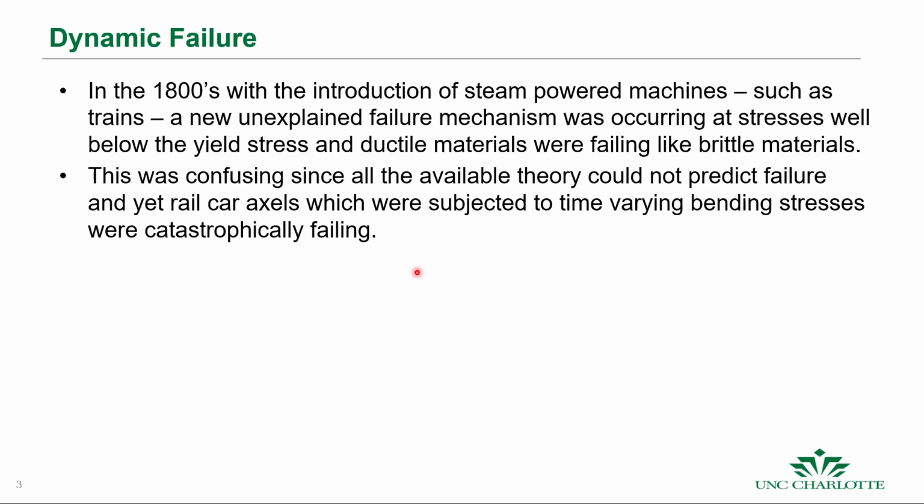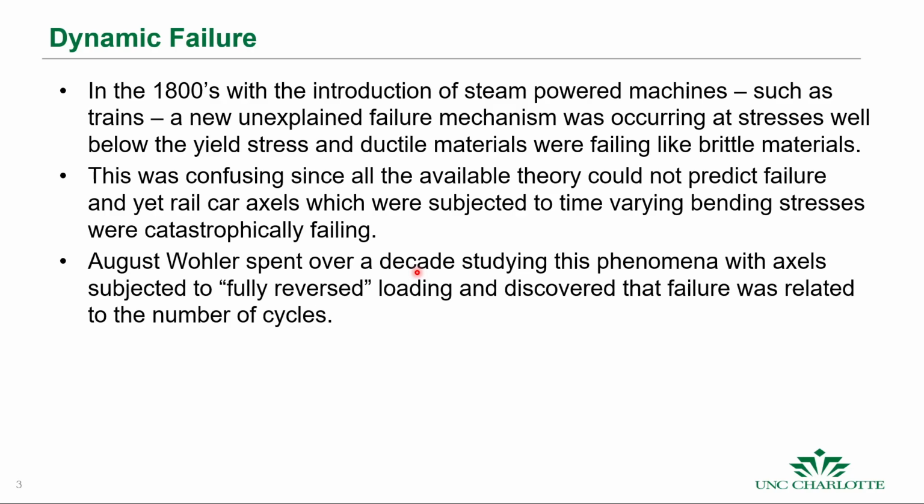We now know that it's because of time varying bending stresses, even bending stresses that are well below the strength of that material. So August Wohler spent over a decade studying this phenomenon with axles. And his axles were subjected to what we call fully reversed loading. That's where we have a positive and then negative load, and it's easy to do in a rotating machine with a suspended weight.